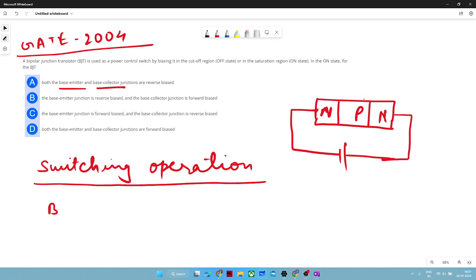So this is a typical signal transistor, but if we want to operate it as a power device, we need to add another layer of PN junction that will be a drift region, and this drift region will help in making it a power device so that it can endure the high level of voltage and currents.